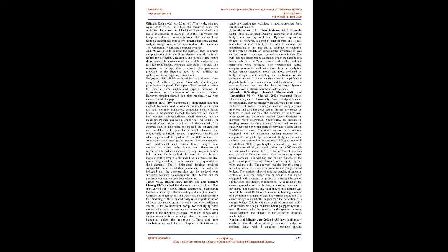James M. W. Brownjohn, Jeffrey Lee, and Bernard Chong, 1997, studied the dynamic behavior of a 100 m span curved cable-stayed bridge constructed in Singapore by full-scale testing and analytical models. Comparison of test results and free vibration analyses shows that modeling of the deck end fixity is an important factor, while correct modeling of stay cables and stress stiffening effects is not so important except for identifying cable modes with weak superstructure interaction which may appear in the measured response.